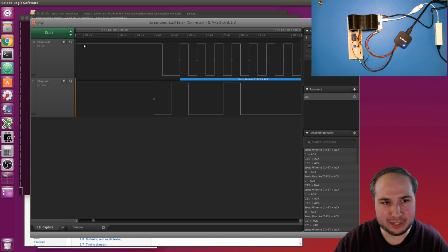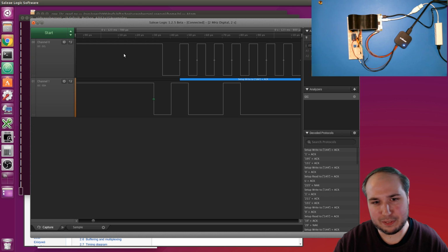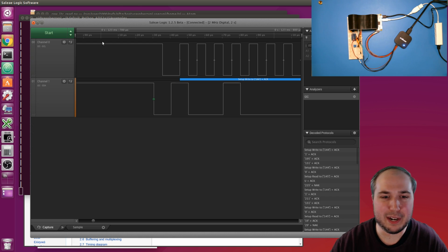And so that's what you see in the logic analyzer here. When the line is up at this higher level, that means it's at like 3.3 volts, so it's being pulled up by those pull-up resistors. When a device wants to send a bit, it actually pulls the line down to ground. That way, multiple devices can be connected to it, and they just have to pull the line down to ground to send a value, whereas each device doesn't have to actually push the value up and down.